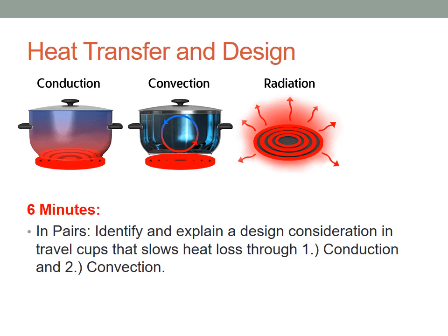So one way, for example, that we make it even better at insulating in a modern plastic travel cup is that we actually create a vacuum. So we have 2 layers of plastic. They're bonded together, and then there's an air pocket in between, or even a vacuum. And because those 2 pieces of material aren't touching, so you've got your inner sleeve and your outer sleeve in terms of a keep cup, you'll note that the way heat can flow through it has been disrupted. Now, the easiest way to show this is in a double glazed window, where you'll find in the middle there's actually an air gap. So if you were to put your hand on one side and somebody else has put their hand on another, you couldn't feel any heat flowing through from one hand to another because of the air gap in the middle. It can't conduct through a vacuum. So that's one way of doing it.